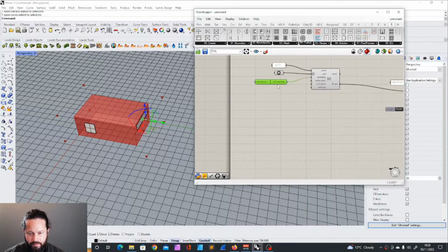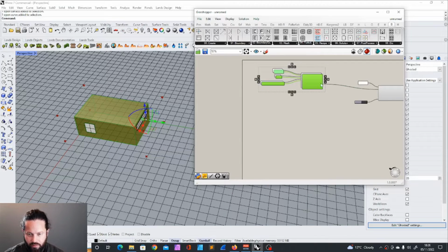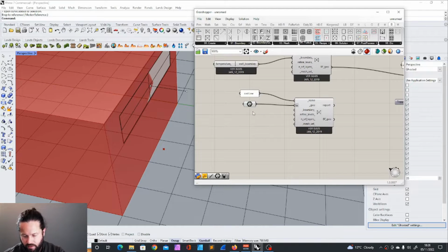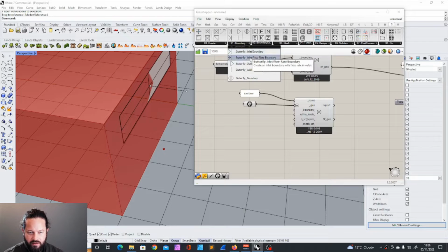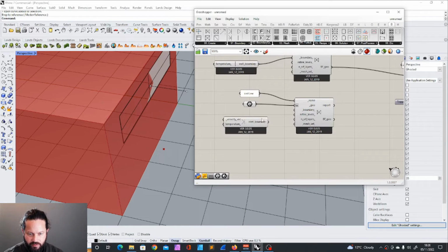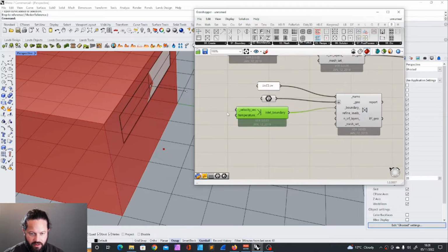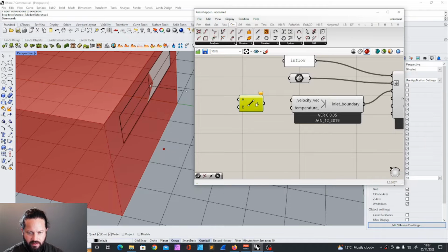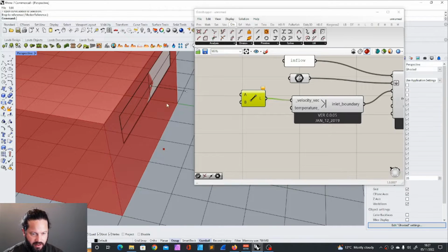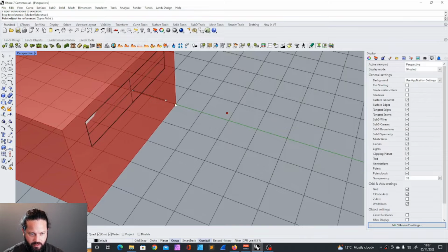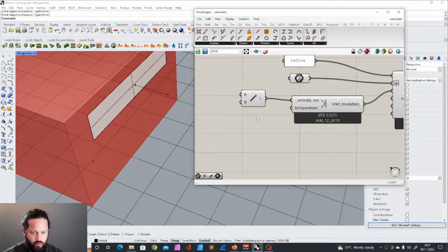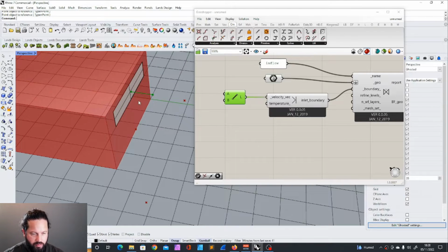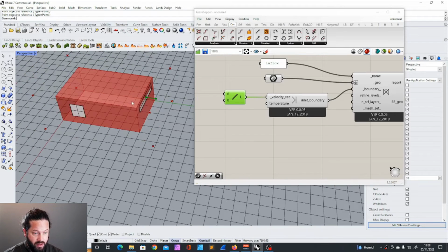We can put this here, and now we can just copy this whole thing. I call this inflow, and this of course doesn't work. We have two options for inlet. Let's use the first one for this, two methods, and we need to provide a velocity vector. We use just a curve here, this tool. We add this here. That's why I added here like this line, and I specify 1 point. It's okay. I have set these 2 points. That creates a vector for me, and the vector is 1 meter long. That also represents the speed of the air, 1 meter per second.